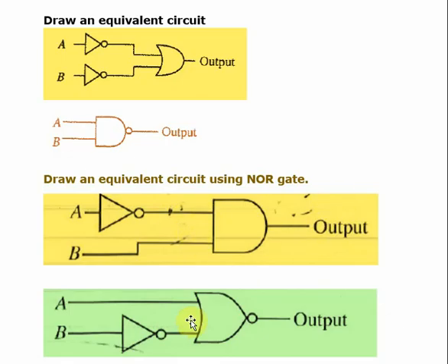Now we need to use the NOR gate, no. For example, now the NOR gate is used. Right? For the NOR gate, the same input should be given, 1 and 1. Here also 1 and 1, we are getting output 0. Now we need to feed the same thing using the NOR gate. That's what the question asks. So you are giving 1 and 1. So what will happen here?